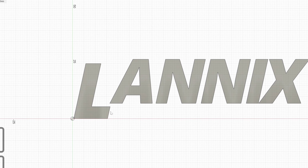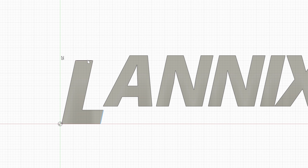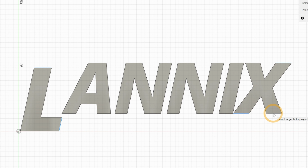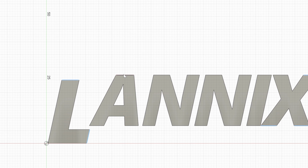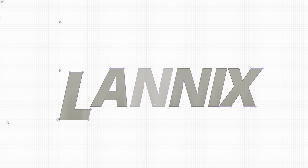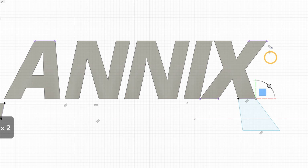Press P to project, then select the 6 edges shown and confirm. Draw lines like so, and be careful not to add any constraints as you go, except for the horizontal lines. Click the check mark to complete a line in space.